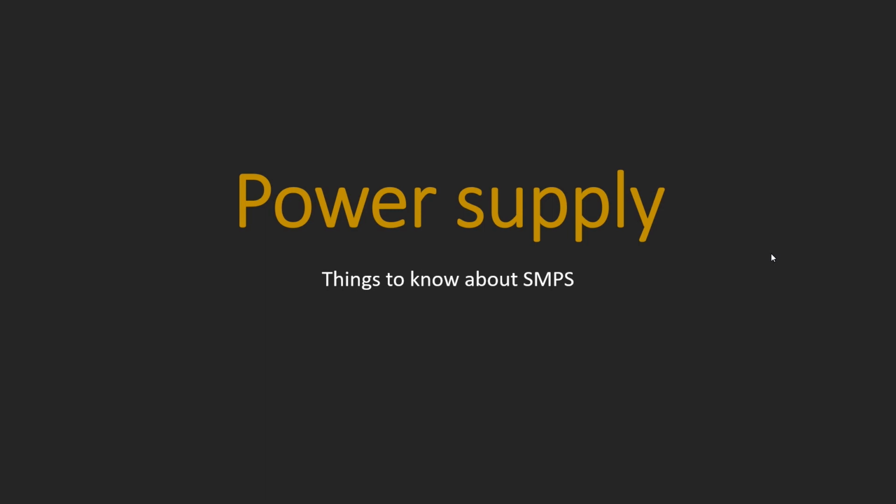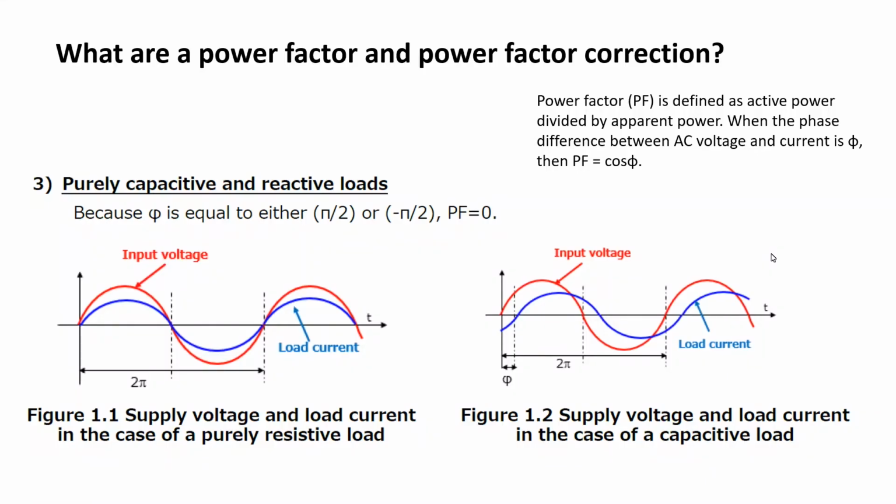Music signal power density is just 1/8 of sine wave signal. We still need 1 kW power capability for 1 kW amp, but we can save on massive heatsinks due to the average power consumption of just about 200 watts. There are certifications regulations on how our equipment uses mains electricity. Switching mode power supply is capacitive load that introduce specific distortions to mains electricity.